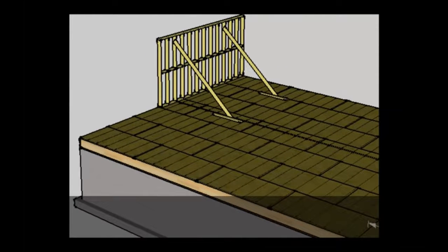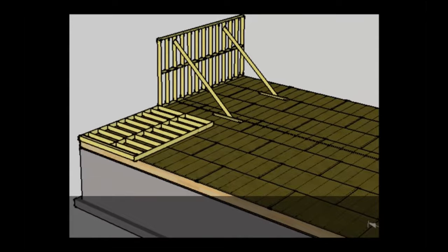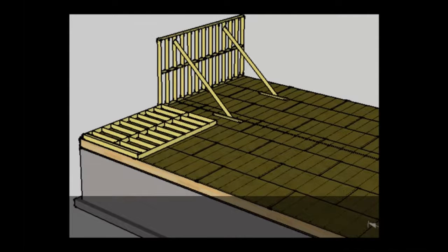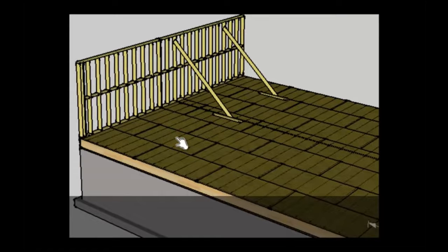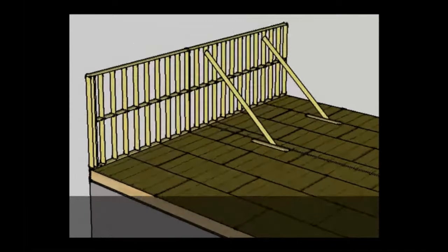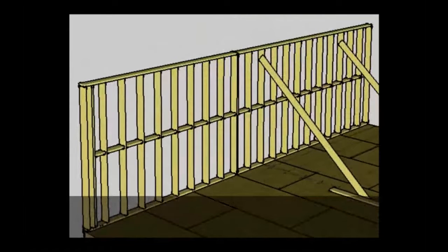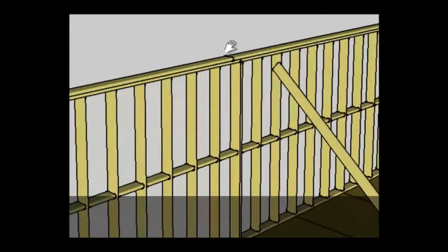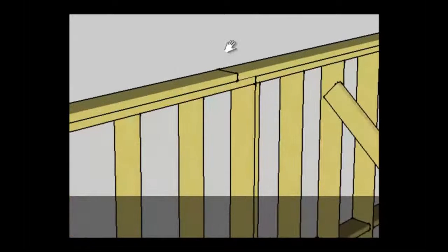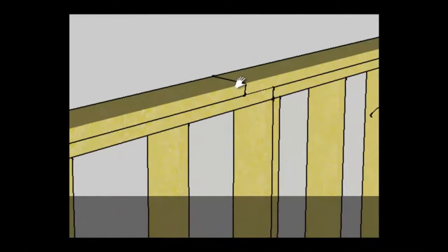walls. Now, what you're going to notice here is that the wall, they did not build the entire wall all in one piece. We have 2 different elements here. The reason for that is because, as you can imagine, the larger section of wall you build, the heavier it gets, consequently making it harder to manage when putting it in place. So they build it in segments, making it easier, more manageable in the installation.